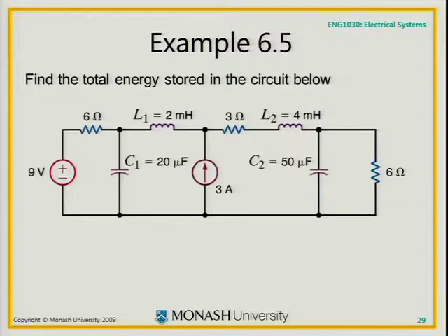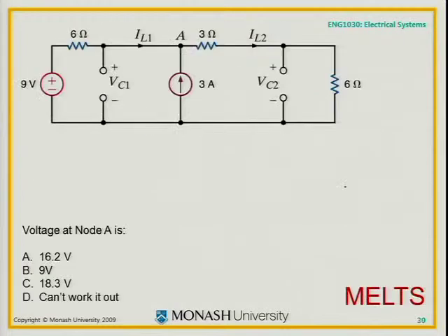So this just becomes nothing. Short circuit, and these become open circuits. So I can get rid of that. The circuit I need to then analyse is that one. There aren't any inductors and capacitors in it. There are short circuits and open circuits where they were.